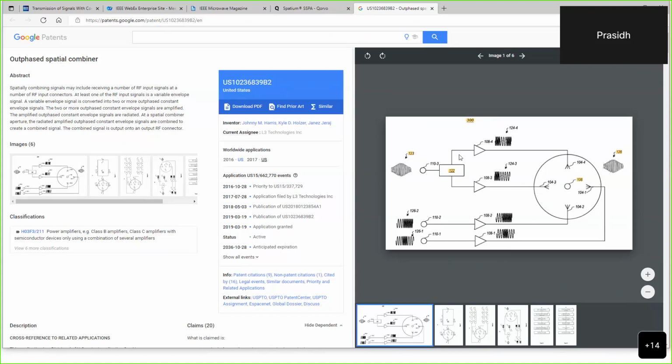And at 90 degrees to that, they're actually applying the Q part. Similarly, in the two opposite arms, they're actually applying the S2, I mean the I and the Q part of S2. Now these signals actually combine in this constrained cavity, and then the combined output is actually harvested using a coaxial probe along the axis of